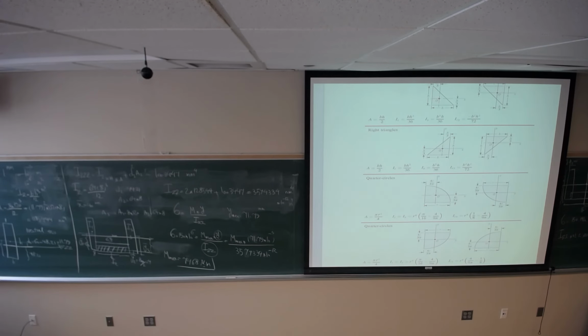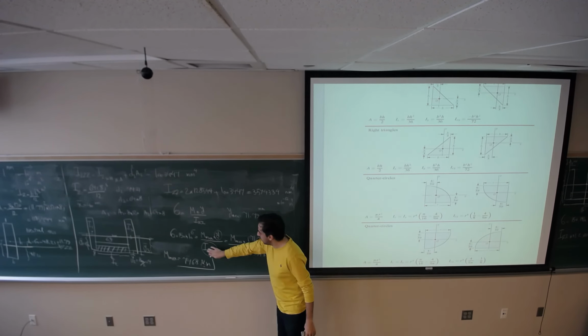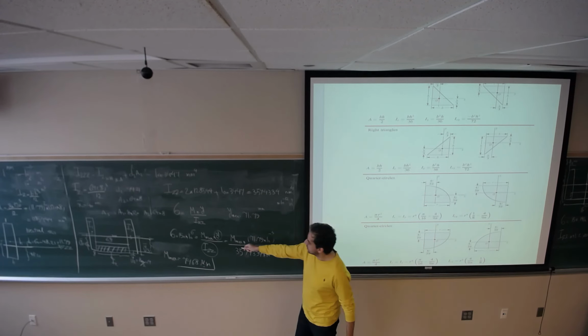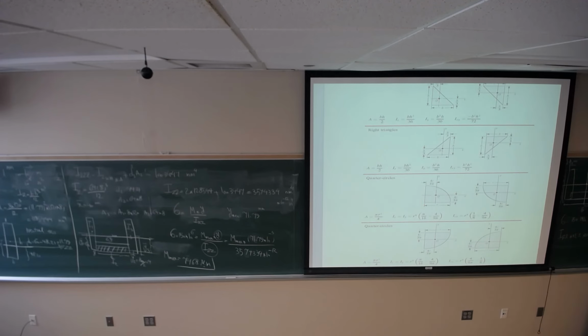So you cannot exceed the maximum bending moment on the critical section. If I ask you what would be the normal stress on this line, the only thing you need to do is plug in the moment, you have Izz, and just plug in Y, 48.21.